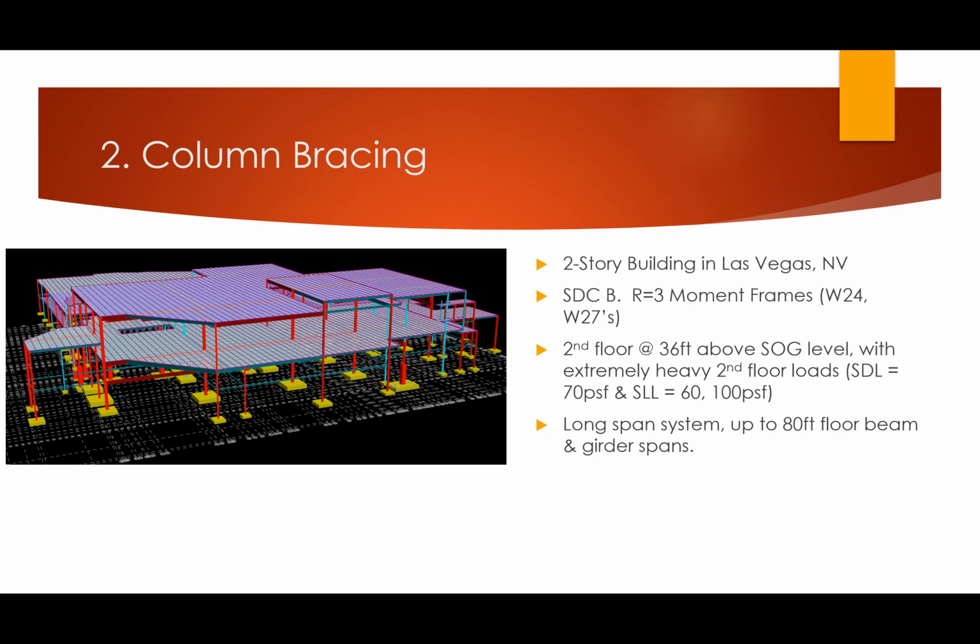Level 1 under here is a gaming floor. And so the owner wanted to maximize and absolutely push the limit with our column to column distances in order to keep level 1 space as open as possible. So we have 80-foot floor girders, and tying into those are 80-foot floor beams. In our worst case, there's a few locations that are different, but very, very long span conditions. So you can imagine we have very tall columns with very, very heavily loaded conditions on them.